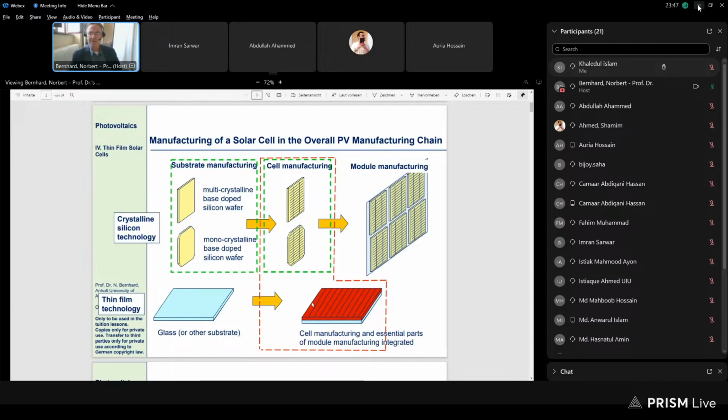Okay, many of the thin film or deposition processes are vacuum processes. For example, physical vapor deposition, which is either evaporation or sputtering, or chemical vapor deposition, which could be low pressure chemical vapor deposition or plasma enhanced chemical vapor deposition. Also atmospheric chemical vapor deposition is possible, which of course is no vacuum process, as the name says. Other non-vacuum processes used in thin film technology are chemical bath deposition, screen printing, spin coating, or doctor blading.